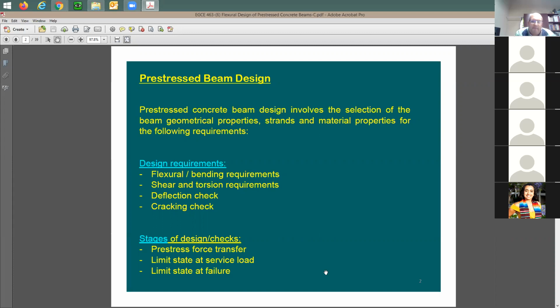The concrete. Other opinions? Concrete, because you'll be able to see it first. Okay. What happens if the steel fails first? It'll be catastrophic. Yeah, it's going to be sudden, right? All of a sudden, the beam is going to collapse. Would you see lots of warning, like lots of deflection? No, it's not going to happen. Just the rebar is going to snap and it's going to come down. We don't want this to happen.